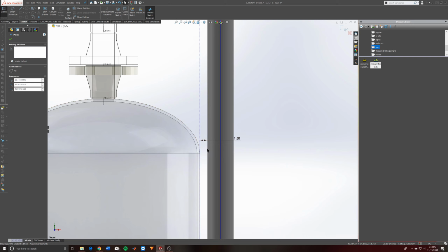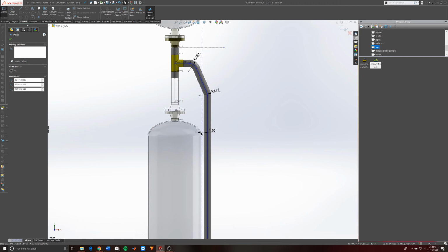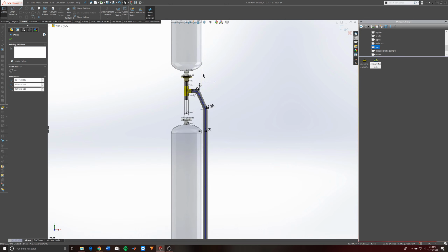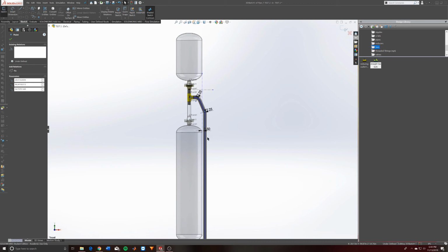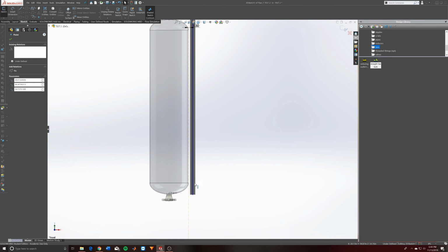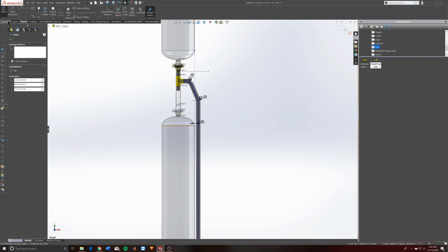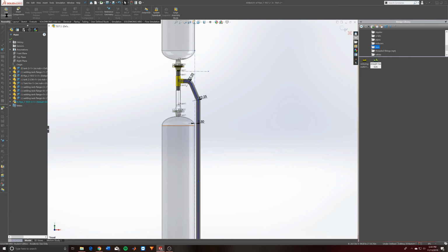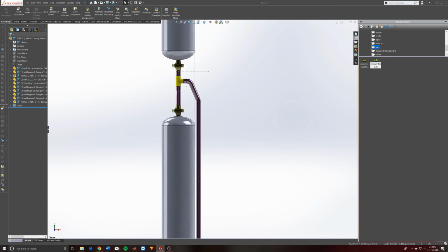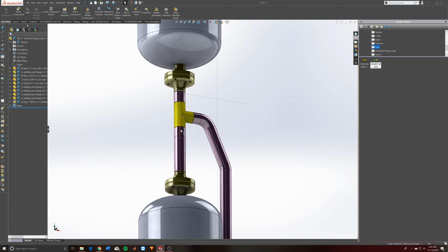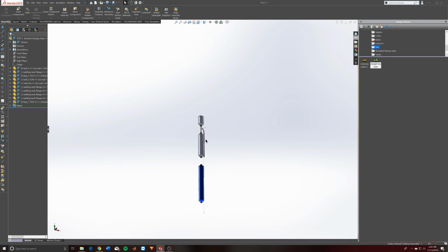But essentially, what I want to do is leave a little space in between the side of the vehicle and the pipe, so then we can add pipe connectors, and later on we're going to have a hood or a raceway that covers these pipes. But that's good for now. We'll leave this guy like that, and to exit, just hit edit component, or you can hit rebuild. Now when we leave, these pipes have joined, and this guy has a pipe going down the side.